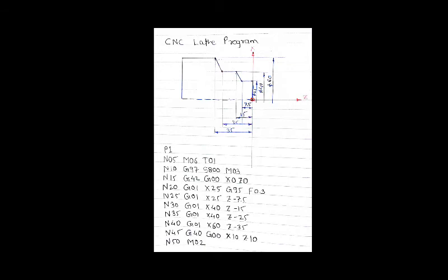So these codes we have used, and here I am going to repeat the three major parts which I told you. First program setup, second chip removal, third one is the system shutdown. In the program setup we did the program setup in the first three blocks, up to N15.